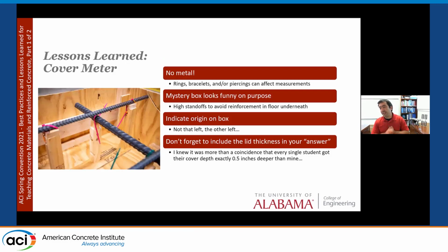With the cover meter, watch for rings, bracelets, piercings. One student had a navel piercing and was holding the device near their stomach, and our device will not randomly, but occasionally recalibrate itself, and it recalibrated to their navel ring, and then they got all sorts of weird data. And that's in the instruction manual.